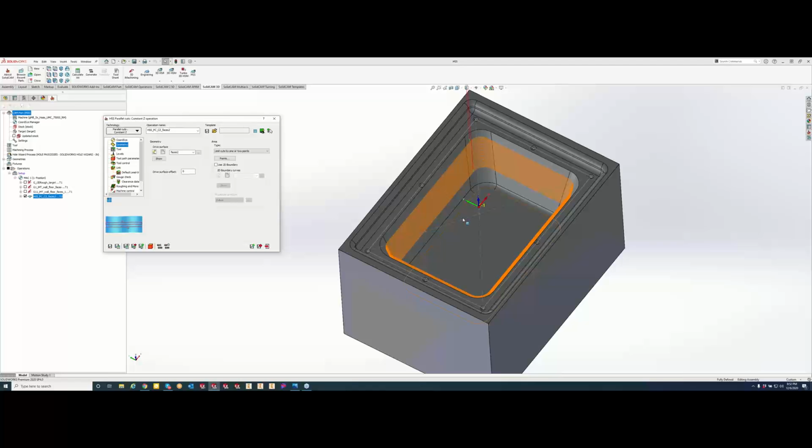The nice thing about this is you guys can create sketch points in there, and you can dimension those sketch points so we have an exact tool path that goes to that exact location. Now, one thing to remember in here is if we're doing parallel cuts, constant Z, or linear, we will only get these three options in here.